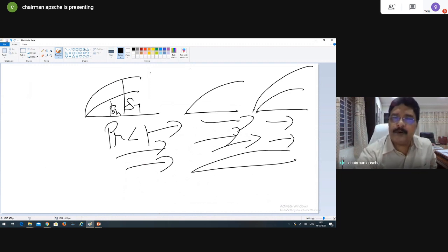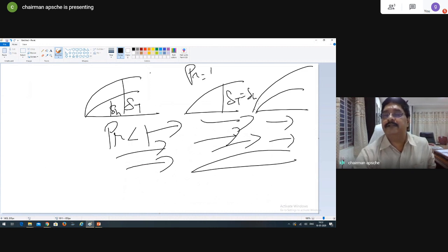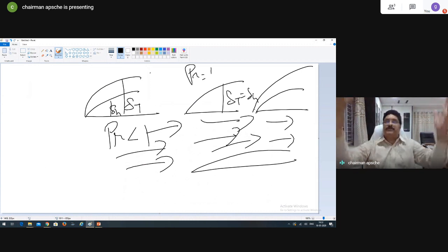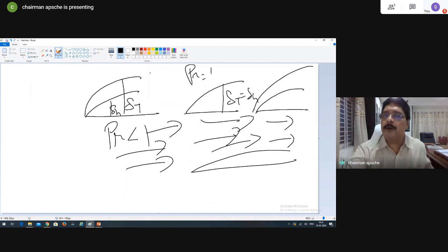So when Prandtl number is equal to 1, that's what I said, delta T should be equal to delta H, because numerator and denominator are equal. The diffusion of momentum as well as diffusion of energy both go to only the same distance, and therefore it is so. So for all Prandtl numbers greater than 1, quite obviously your numerator should be high.